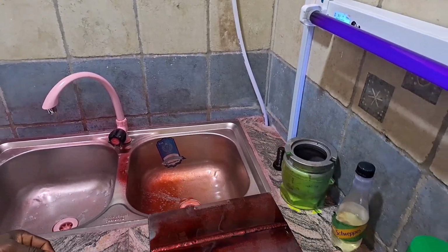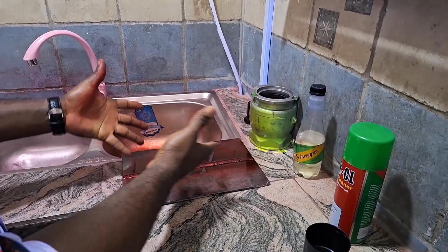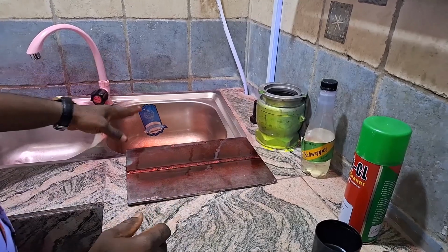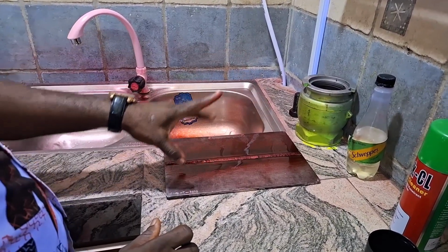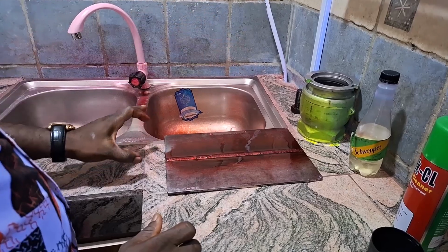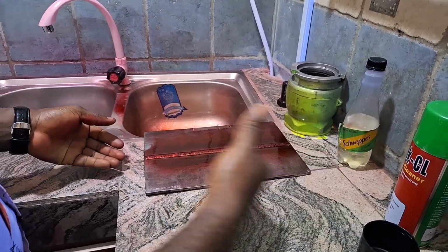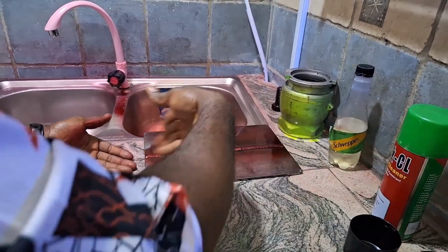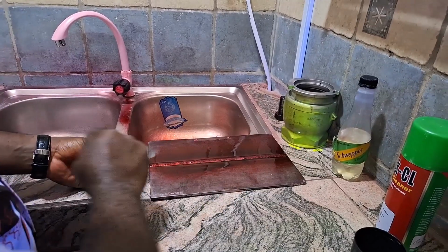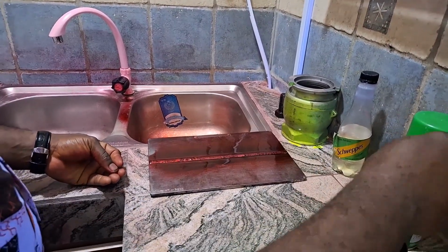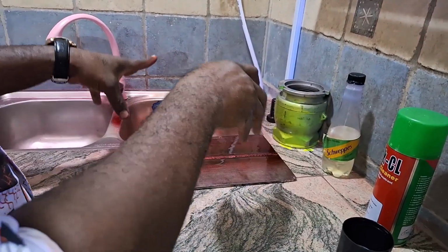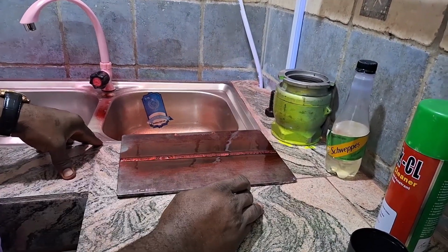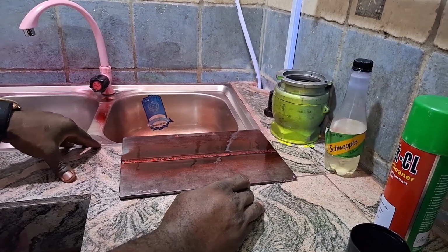We could also use a brush, because with this whole spray, you see how messed up this place is and the quantity of penetrant that we are using. So you can just decide to put some quantity somewhere and apply with a brush. You can dab with a rag or something, just dab it on top, but just put enough for it to allow your process to go on.